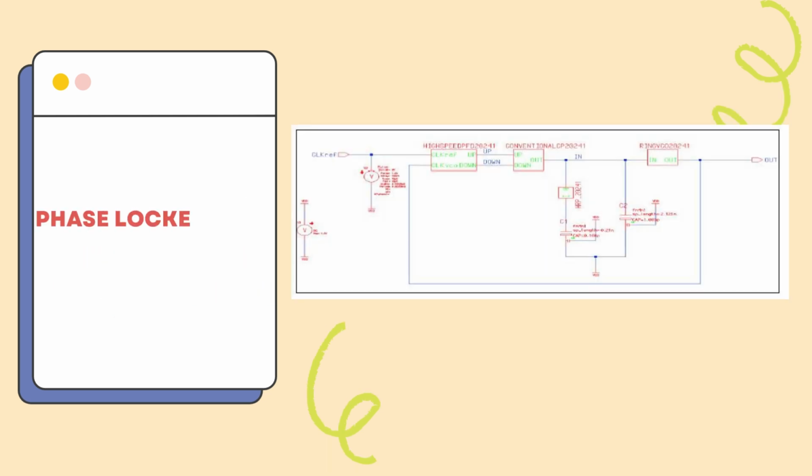After designing the schematic and layout for each sub-block, it's time to bring them all together. This diagram illustrates the complete PLL system in a test bench configuration, showing the crucial interconnections of its four fundamental building blocks: the phase frequency detector, PFD, the charge pump, CP, the passive RC loop filter, LF, and the voltage-controlled ring oscillator, VCRO. This test bench operates exactly as we outlined in the initial PLL block diagram.